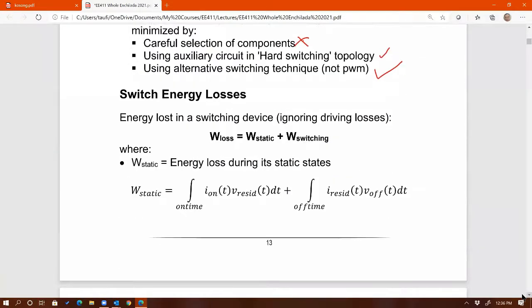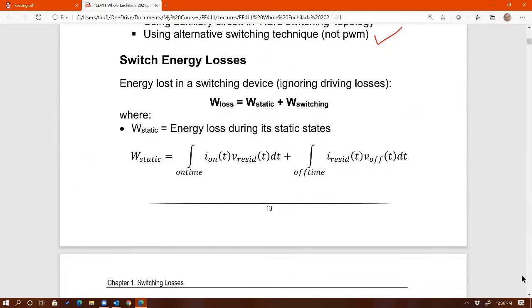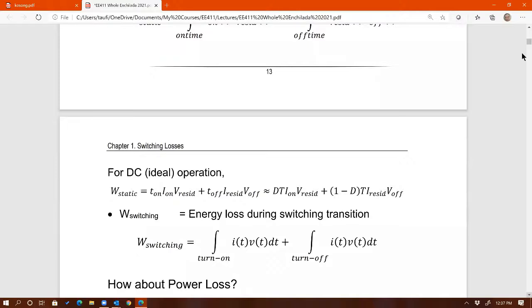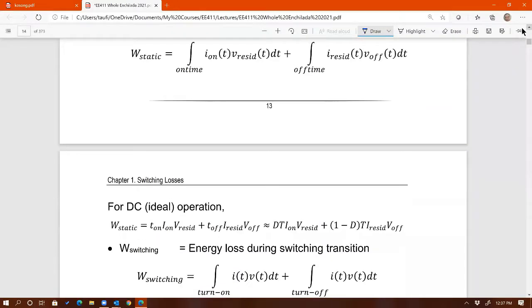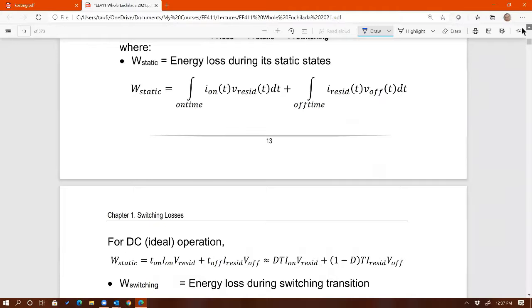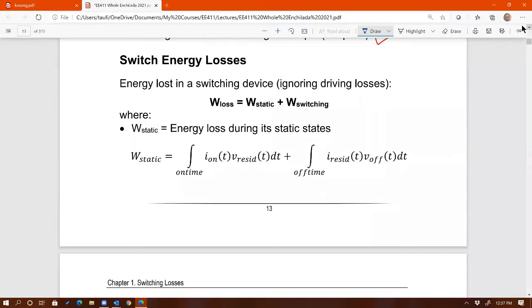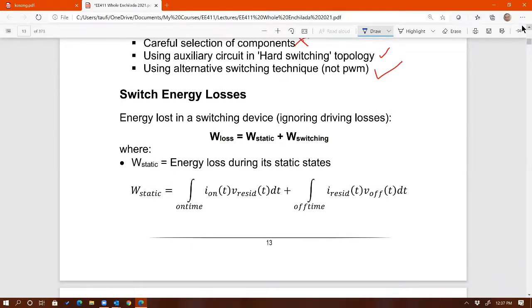method. I actually got to use it at least once in my previous experience. I helped design a soft switching converter for medical equipment. It was a high voltage DC supply, 120,000 volts DC at 40 kilowatts. Especially for those kinds of applications, you do need soft switching, because PWM is great, but when it comes to high voltage, high power, you're going to end up with lots of noise, lots of switching loss, right?